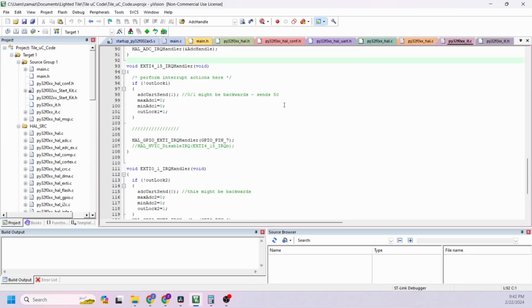To implement this, I did some trickery using the other two timers. The general idea is this. When the interrupt triggers and sends the ADC value out, I set a flag that basically says already sent, and it locks out that interrupt code from repeating until that flag is cleared. The harder part is figuring out when to clear that flag.